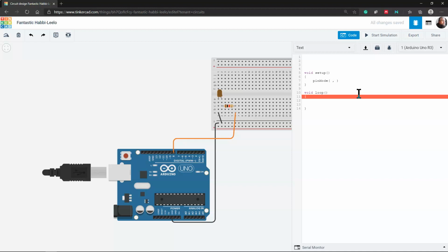And I'm doing this from memory. Make sure, okay, Python people, there's your semicolon when calling functions. I'll do this from memory, and if it doesn't work, we will look this up on the actual Arduino IDE, if I don't screw this up. So the first thing should be the pin number you want to work with, which is 8. And then next is saying whether it's supposed to be input or output. And this should be all in capitals, based upon my memory of it. So we want it for output for controlling, so I'm telling Arduino, okay, pin 8, we want to use for output.